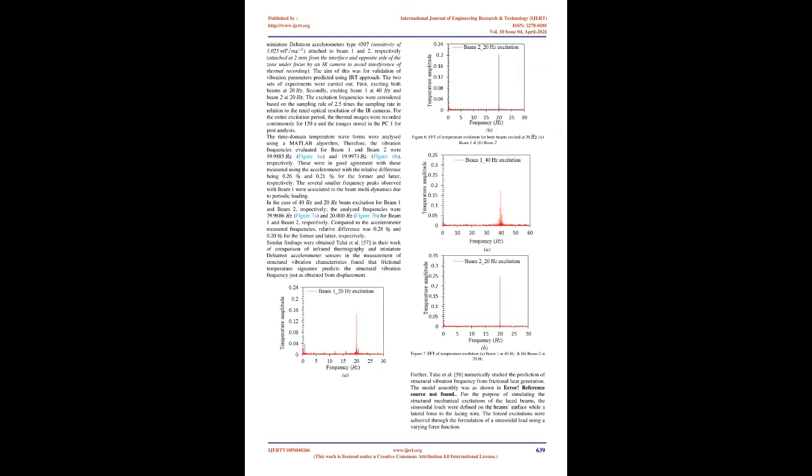Experimental methodologies for IRT-based condition monitoring. A typical industrial application of IRT-based condition monitoring on a dynamic mechanical component, a compressor motor, including its thermal image, is presented in Figure 2, where abnormal surface temperature is an indication of probable flaw. Accordingly, despite the large amount of research conducted on condition monitoring using IRT as indicated in the recent comprehensive literature review by Bagavathiappan et al. [2], little attention has been paid to vibration measurement.